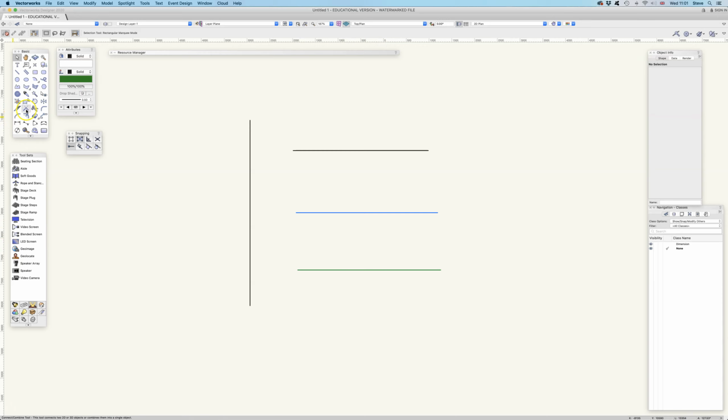So, Connect and Combine tool, first of all, we have 4 options. Forget the roof, mitre roof face joins. That's not really for us at the moment, more obviously a building thing. We're just going to look at the lines. So, this first option here just extends the line that you click to another bisecting line. Any line that's kind of going to cross its path, it'll extend it out. So it's kind of useful for tidying up, I suppose. That's an option. I'll just undo that using Command Z or Control Z if you're on a PC.